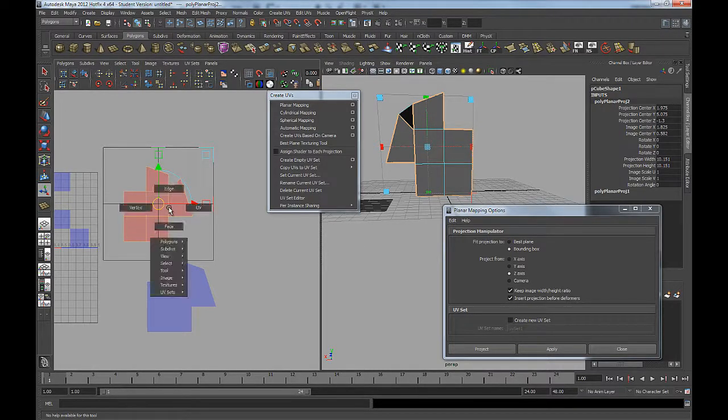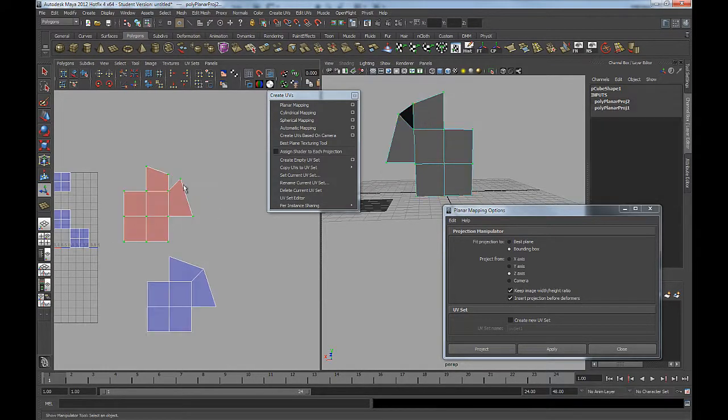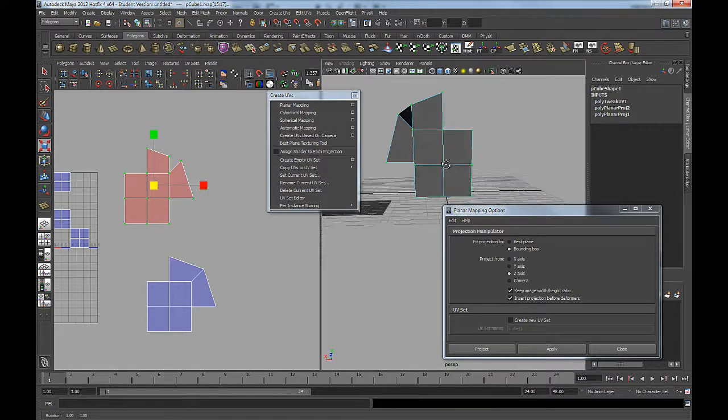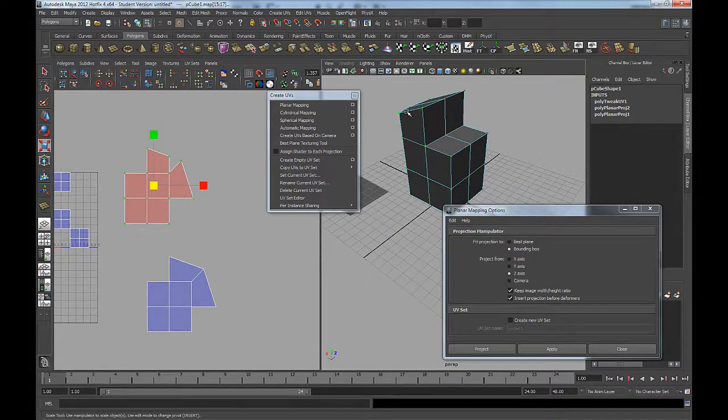So what I'm going to do is right click and select UV mode, and then I'll drag a box across those parts. So you can see these little UV dots. A UV point is a little bit like a vertex, except it's used in UV space. You can move them around using the move tool like this. You can rotate them, and you can scale them the same way that you would with vertices or polygons or edges, except they can only be edited in the UV template. All right. Notice that even though they're selected and visibly selected over here, we can see the little green dots.